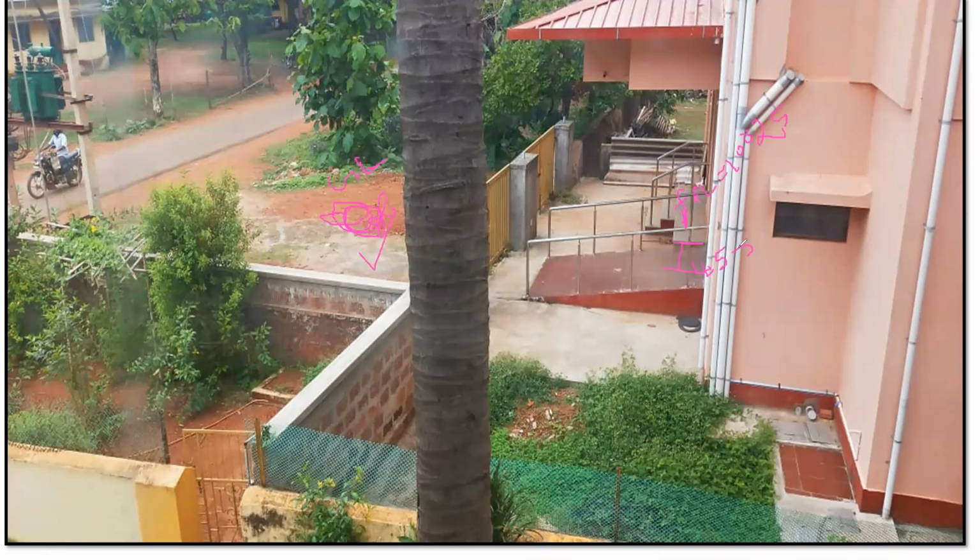Now, how much it has to be depends on the client, the type of project that you have, and also the road that you have. See, the road level is here, so you cannot afford to construct a building below this. You have to construct above this, because during the rainy time the water will be stored here. All the water from the road is going to flow in this direction. So if your floor finish level is below this, then obviously the water will enter into your building. That is why we always try to keep the floor finish level above the road level, right?